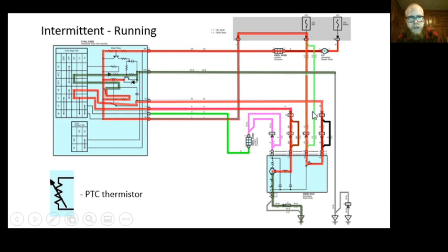The park function is built into the wiper motor. So unless something over here burned up in my off, like this piece right here, then I would still have park. And so it limits it. It's like, well, I know it's not the motor. I know it's not a bunch of these wires over here. It could potentially be this wire that goes to ground over here. I'll give you that much.